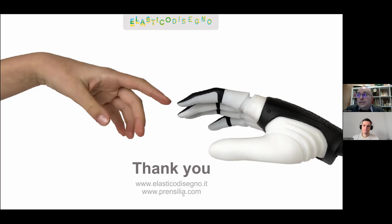Well, that's one of the reasons for the changes that we've done. We've done 3 or 4 iterations so far on the fingers. At first, they were overmolded in the same kind of softer, flexible silicone used for the glove. But over time, the overmolding was not gripping enough on the 3D printed part. If you stick your nail in where the two materials join each other, you could just peel it off. And so we've experimented with different hardness of silicone.